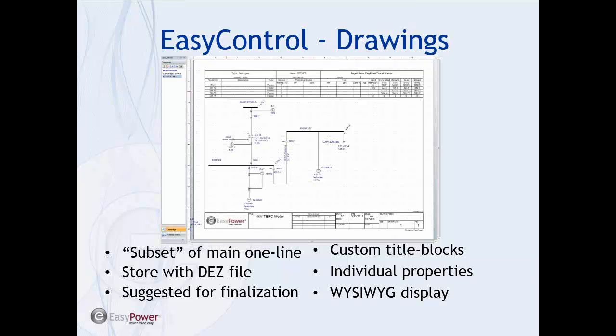So what we do suggest is that you wait until the development of your base case is finalized to create drawings for your one-lines. It's a good opportunity to really go back through, make sure that you're not missing anything, that you have everything that you were looking for, all your panel schedules are filled out correctly, and get back into that one-line and improve it for the better.